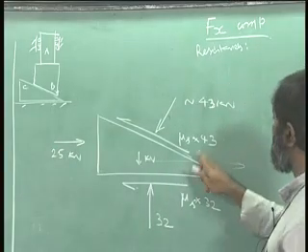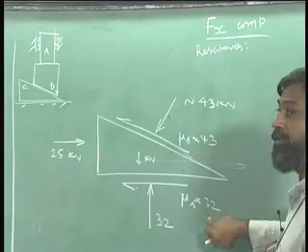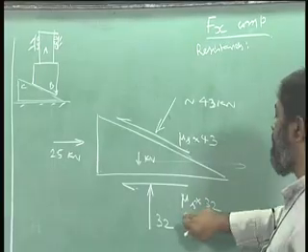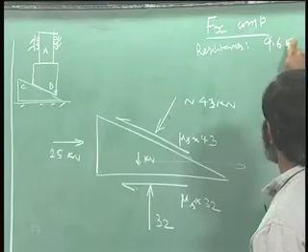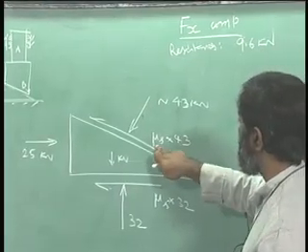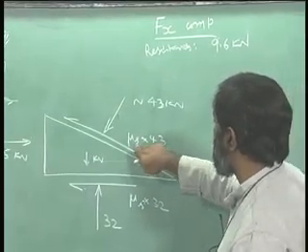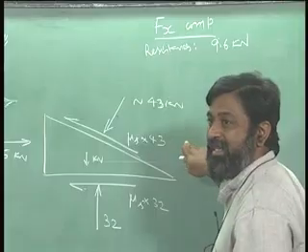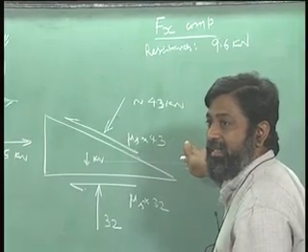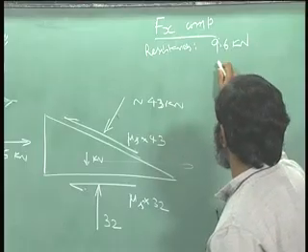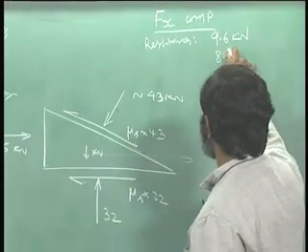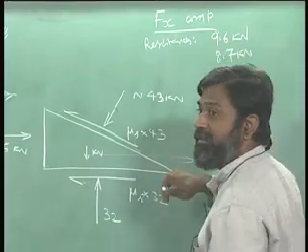One resistance is due to the friction below, that is 0.3 times 32 is 9.6 kilonewtons. This we already found out is mu s times 43 times 0.7 or so. So that came out to be around 8.7 kilonewtons, right.